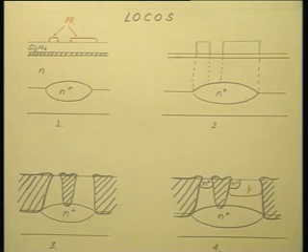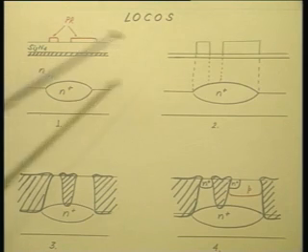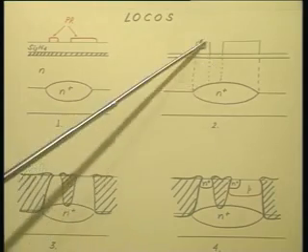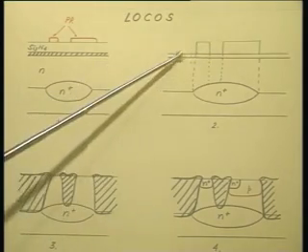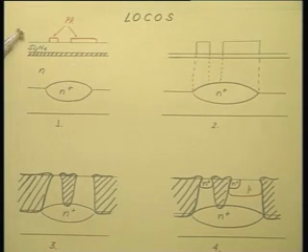In the next figure, using these photoresist masks, I have etched silicon nitride from the remaining portion. So, that I have silicon nitride only existing in these two regions, and underneath there is this pad oxide, and silicon nitride is etched from all other regions. So, now you see the equation is very simple. The regions which are not protected by silicon nitride will get oxidized. If I subject it to oxidation, the regions which are not protected by silicon nitride will get oxidized.